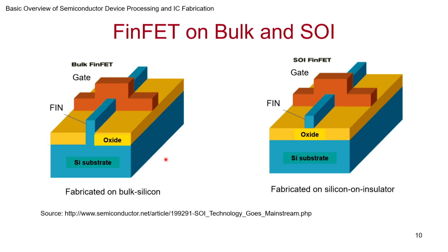Now it turns out there were lots of groups which were also using silicon on insulator. That is, you had this thin crystalline silicon on a complete insulator, as is given in this case. And in this case, actually the fabrication process might be to some extent simpler. You have this thin silicon, you need to just pattern this into a fin, and you don't have to worry about etch stop and all, because the oxide is there. Silicon and oxide, we can easily have a differentiation. Selectivity can be quite good in the etching, and then of course you do the rest of the pattern as in this case.